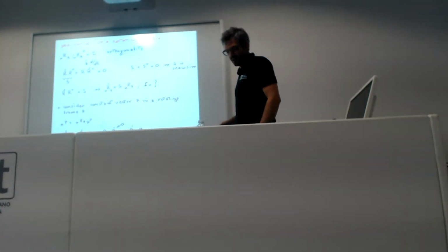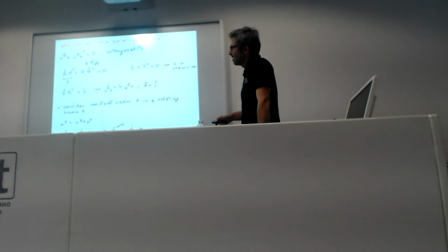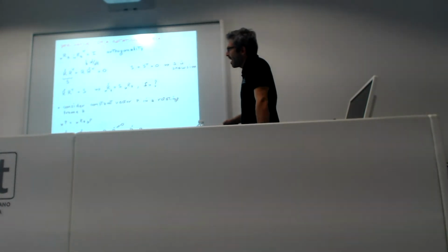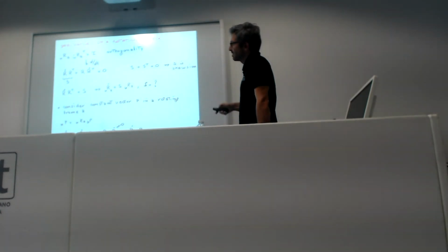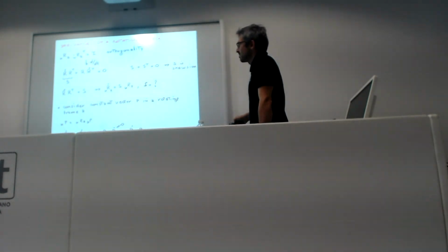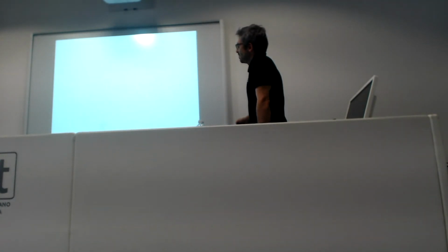We map the point in the moving frame into the world frame, and if we differentiate, we get the first term, the derivative of R times p, plus the rotation matrix times the derivative of p. But that is zero because p is constant in the moving frame, so we get p dot w equal to R dot p b.